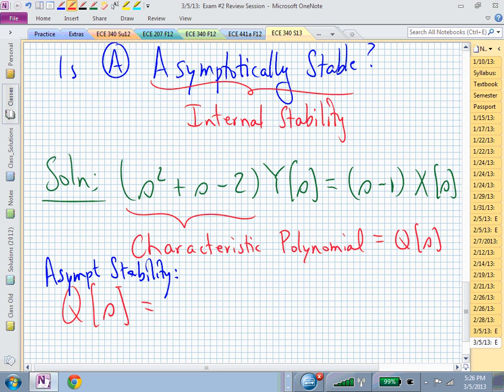So now what we have is the system stability, just the generic system, and that's what asymptotic stability basically governs. Then we have input-output stability, which is BIBO stable, and there you could have pole zero cancellations that cancel an unstable internal mode that you don't see between the input and the output. It's not something you really want to design or have because it's going to burn up. You're going to have a bad system if you have an asymptotically unstable system. But this is just a theoretical concept to get you thinking about what is possible.